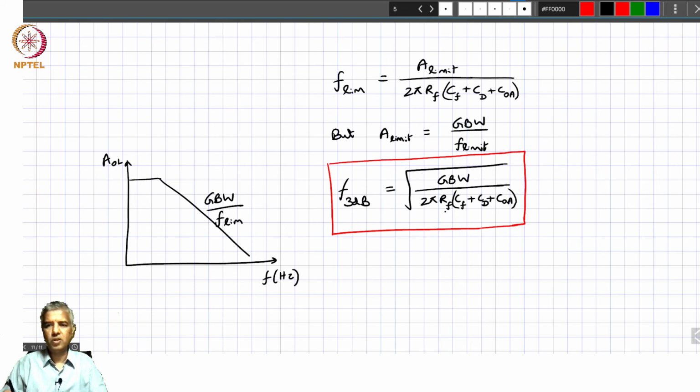So as you increase your reverse bias voltage, you would typically find that this capacitance, the ability to store charges within that diode, actually reduces as you go to larger reverse bias. Okay, so the capacitance value could be reduced because of that. So let's actually look at some realistic values for all these different things.